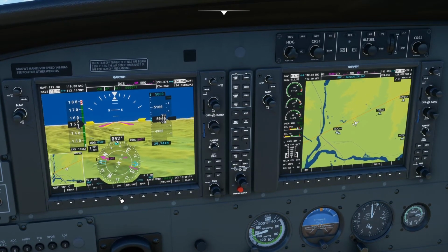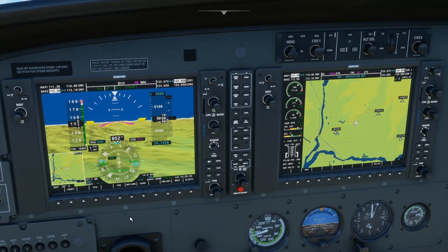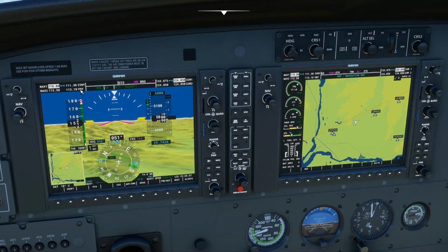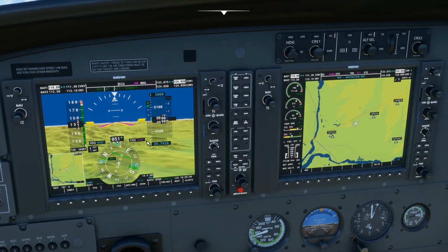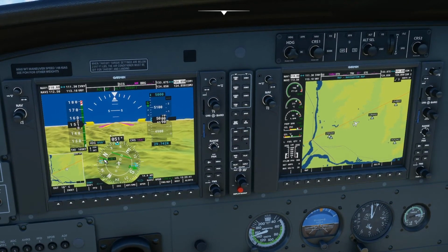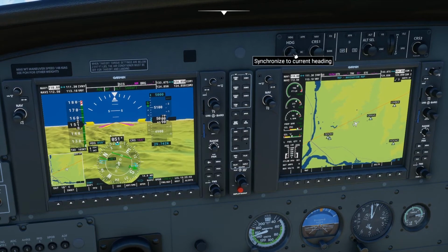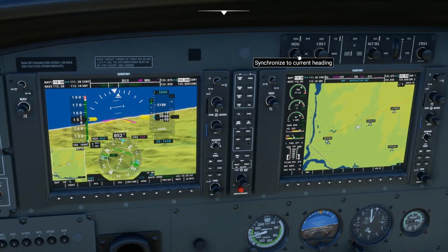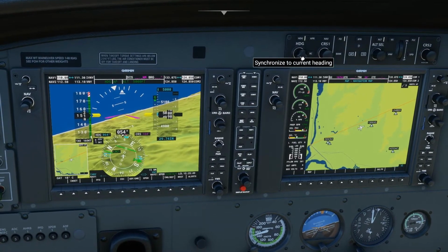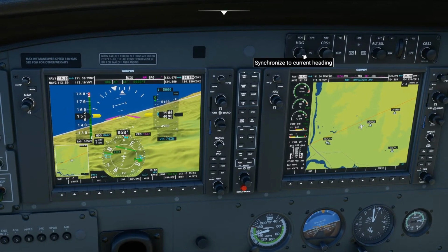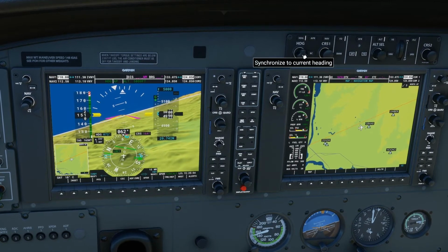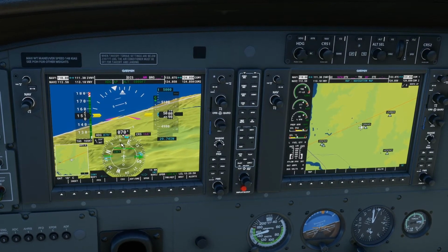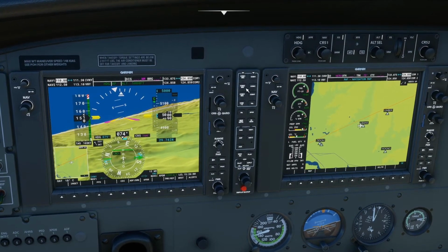So now we're gonna change here to VOR1. On VOR1 we need to set to the ILS, India Victor November Yankee. That is correct. So 332, there it is. We are crossing the lead radial, so I'm gonna set heading here and start turning to intercept the 164 course, which is the localizer. So we have here localizer signal.